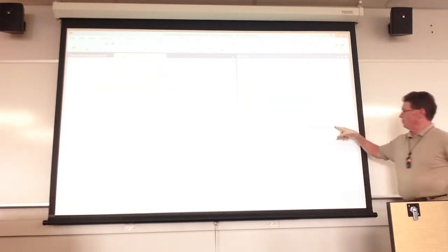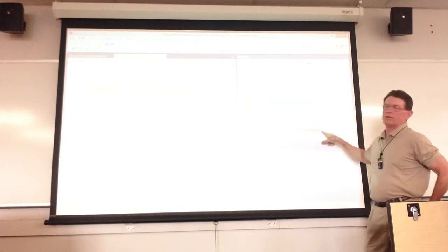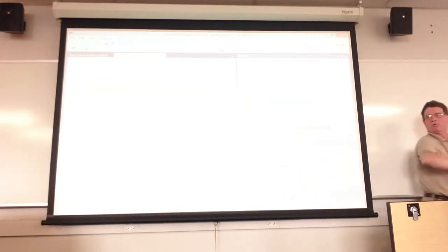So here we're just going to single step through. Now we're going to output it, and here you can see you just loaded up all the pins for the data direction register for port B as high, which is now going to force them to be outputs.